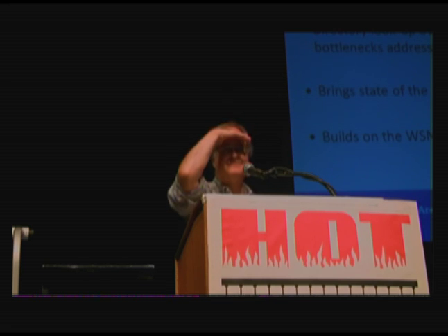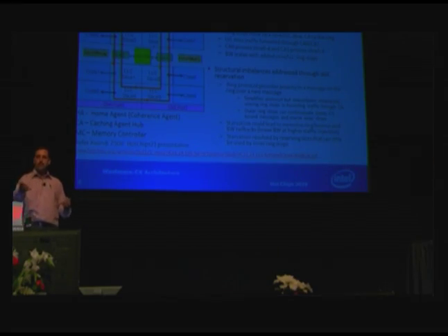Sure. Hi. I have a question on the cache structure you showed initially. You had a ring topology, or a double ring topology. I'm James Tringali from Rambus. You said it's distributed and shared. So does that mean there's a kind of variable latency if a core misses and needs something in the cache? Yes, we're quickly getting to non-uniform cache access kind of issues. There is variable latency depending on whether the address hashes to a local slice or a remote slice.